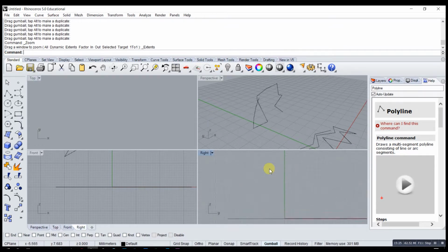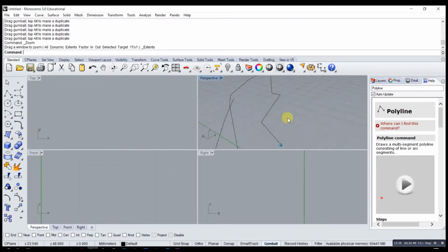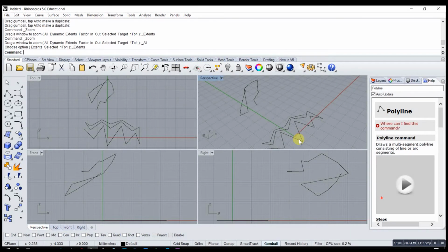So even if you go back to the 4 viewports, and let's say you've zoomed in on a bunch of them, and you're just really lost and you're going, oh God, what do I do here? If you hover your mouse over the zoom extents button, you'll see here, this will be the first time we've talked about this, that there is a different function for which mouse button you hit underneath zoom extents. If you hit the left mouse button, it'll do zoom extents. If you do the right mouse button, it'll do zoom extents all viewports. You see that? If I hit right mouse button, it zooms them all back to display the items in all viewports perfectly.